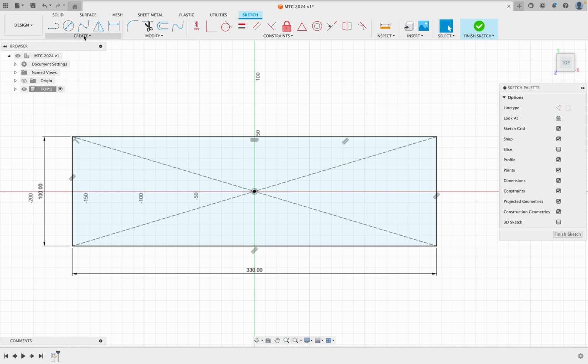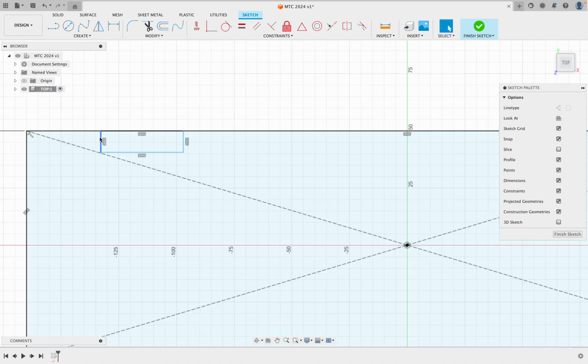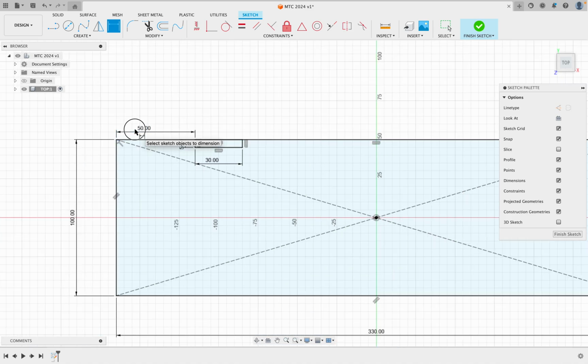Okay. Next here, I want to create the joints that are going to allow me to connect my car. 2-point rectangle, click, drag, drop, escape. Okay, you want to make sure that you click on that line. Then I'm going to dimension it. Dimension, simply right here. I'm going to dimension this to 5 millimeters. That's the thickness of our wood. I'll stick 5. Okay, I'll make this out to 30, like so. And I'll make this from here to here, those little nodes, 50. Let's make that 30. That'll just be a little bit more symmetrical, 30.